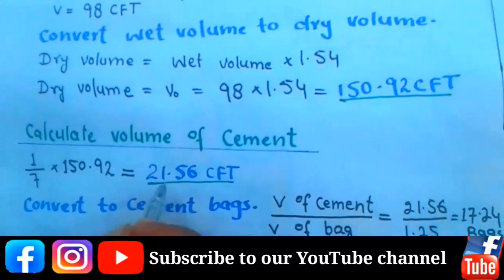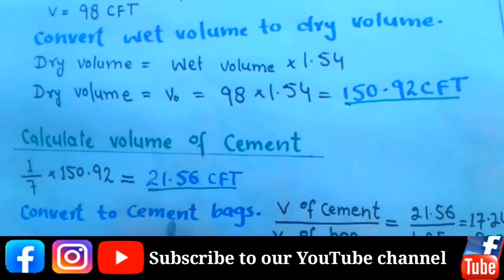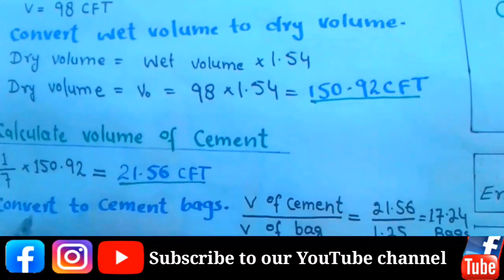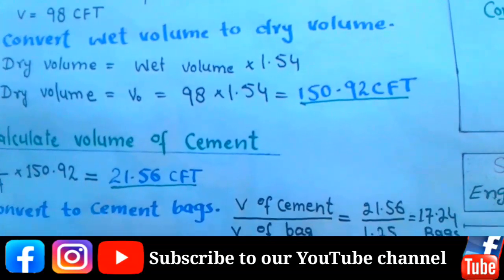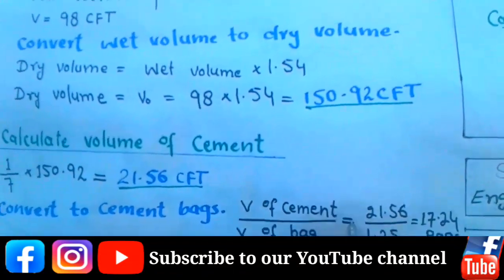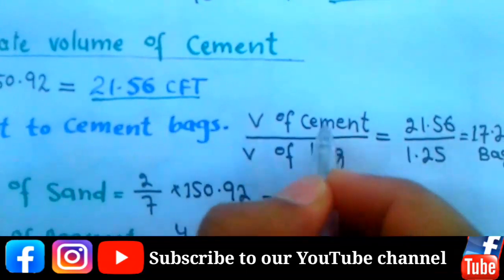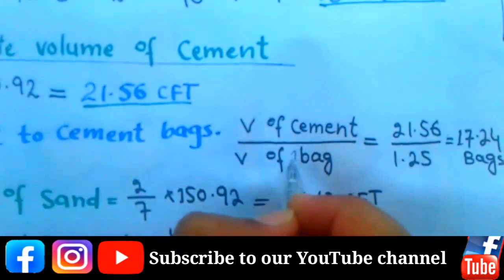So we have to convert this 21.56 CFT into bags. We use this formula to convert to cement bags: volume of cement divided by volume of one bag.